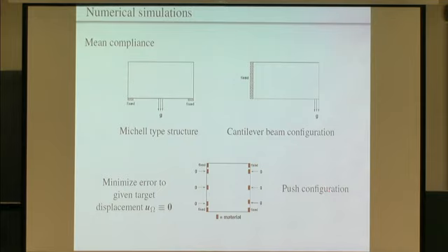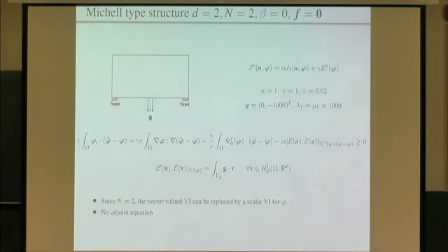But when we looked at the L2 compliant mechanisms, to get some sensible computations, we saw that we actually needed to fix regions in the domain where we set material. This is our set S0. In all these red parts of the domain, where we fix the boundary and also where we impose our boundary forces, we prescribe there to be material. So in the Mitchell type structure, what are we doing? This is just in 2 dimensions. This will just be a single material, so there'll just be material or void.